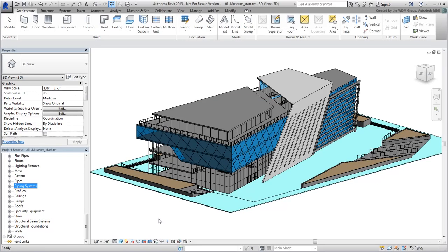Let's see what else we can do that's obvious enough. Typically, you want to make sure most of your materials are set up properly in Revit. The better they are defined in Revit, the less work you'll need to do in 3ds Max. It is inevitable that a few material definitions will need adjustments, but do try to set as many as you can early on. Case in point, this brown surface representing grass currently is assigned with a brownish material. You can easily change that, so you don't have to do this kind of work in 3ds Max. Ultimately, it boils down to which 3D application you're more comfortable with, but I personally like to tweak the Revit model as much as I can.